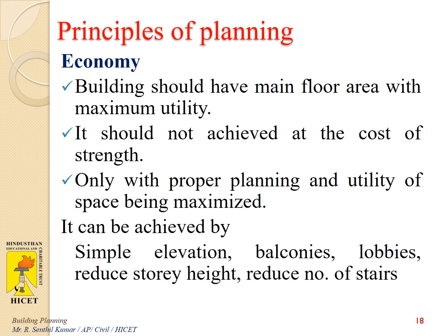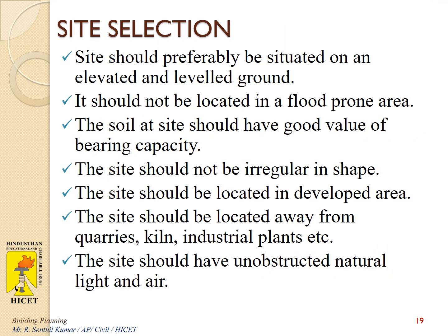And then economy, the building should have main floor area with maximum utility, and it should not be achieved at the cost of strength, and only with proper planning and utility of space being maximized, that is, the passage being minimized. It can be achieved by simple elevation, providing small portions for balconies, lobbies, and reducing story height and reducing the number of steps in the stairs, and standardization of size of various components and also materials.